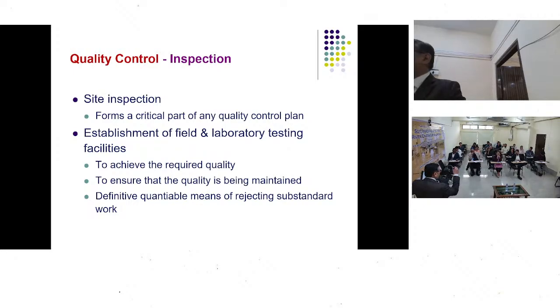For settlement of a clay particle in that pipette analysis, how much time does it take? Suppose that is X hours. I'll not give the answer. So my test will be completed in X plus some T hours. Means, if I'm going to have 5 samples, it is not less than 2 to 3 days before I'll be able to complete one test.